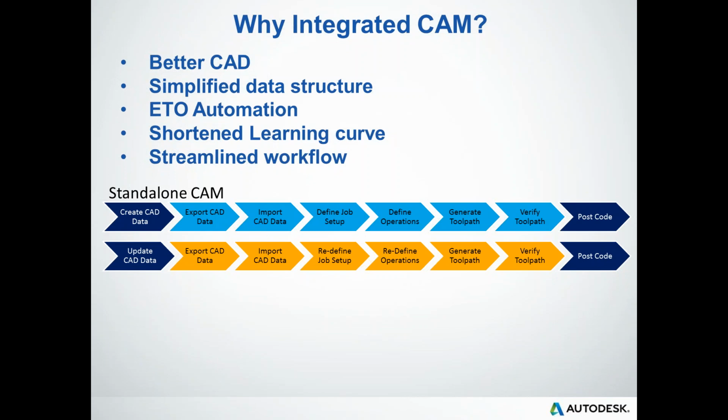Engineering changes happen, then you've got to re-export out and re-import in. This is why integrated CAM is really the future, and really shortens and streamlines your workflow. We don't need to do any more exporting or importing. Those days are gone. In fact, we don't even really need to define the setup, because the software knows that a change has been made, and you'll be flagged by that on the CAM side, so that you have to verify your toolpath and regenerate if need be.